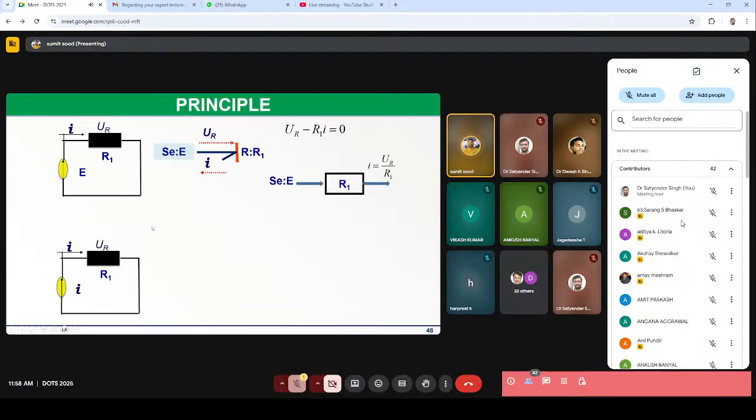So we have different conventions for different components that we discussed in the beginning. For a source of effort, the causal stroke is always on the arrow side of the power bond, because it is going to give the effort to the system. And in the case of a source of flow, it is on the left side because it is going to give the flow to the system.